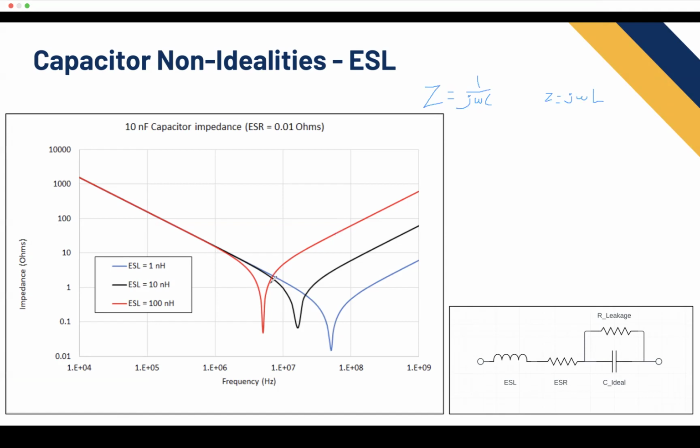And when you have a resonant circuit like this, this peak down in the middle is actually at the frequency 1 over square root LC. So that's a quick math you can do to find the resonant point of your circuit. And how deep the point of that resonance is depends on your equivalent series resistance. Now, all the things I'm saying are not specific to this implementation. This is true for any inductor, resistor, capacitor in series.